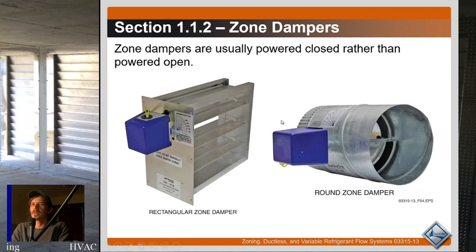Alright, so these are normally open dampers. The dampers are normally open. And you'll want to remember that. Zone dampers are usually powered closed, not powered open.